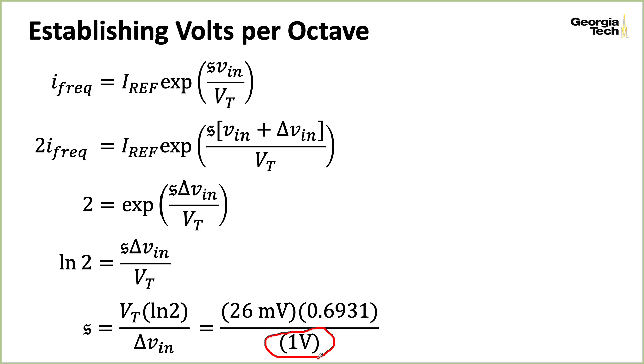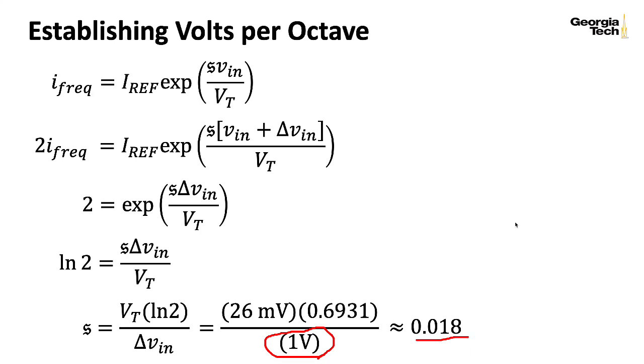That's kind of fun. It's a bit more awkward in terms of half steps because you have something like 83 millivolts per half step instead of 100 millivolts per half step, like with the Buchla standard. But this is the most common one, so we'll go with it. Anyway, multiplying all this out, I get a scale factor of 0.018. So put a pin in that, 0.018. And it's also useful to view this as a fraction, which I'll write as 1 over 55.5. Keep that in your head as well.